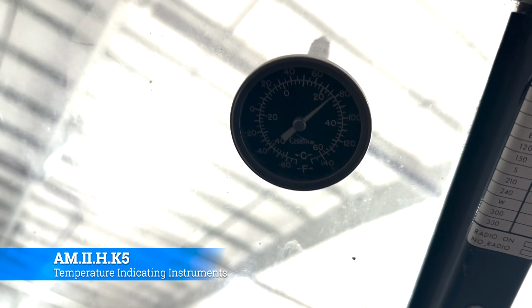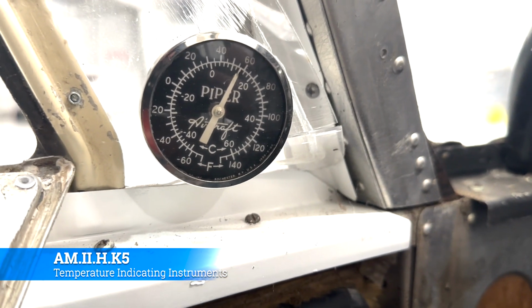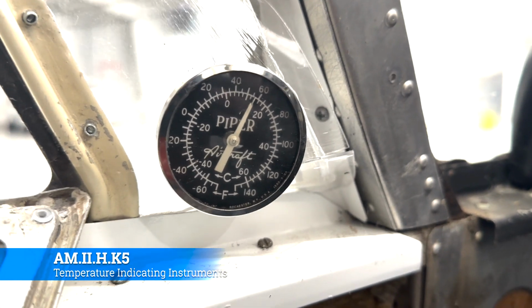So let's look at what the 8083 has to say about temperature measuring instruments. Temperature measuring instruments can come in a variety of forms. They look a little bit different on every single airplane that you get. Like on the Aztec and the Cherokee, they're both inside the windshield. You screw a hole through the windshield, you stick a probe through there, you put a shield or a sheath on the probe and tighten them up, and it just sits inside the windshield that way. On the Lear, it's totally different.